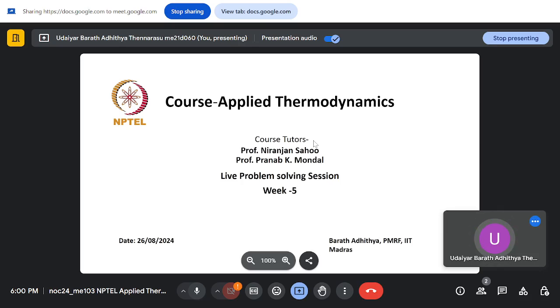So the Rankine cycle was basically we started with the Carnot cycle, which is the basic cycle which will give you a maximum efficiency. As the Carnot cycle had practical difficulties, which we saw, we changed some of the Carnot cycle processes, and we got a Rankine cycle. This happened inside a two-phase dome, because we cannot have a constant temperature process anywhere else. So we went inside a two-phase dome for a pure fluid which will have a constant temperature. You can change that constant temperature into a constant pressure process, so we will still get some region which is at constant temperature. So that was the idea, and we went from the Carnot cycle to a Rankine cycle.